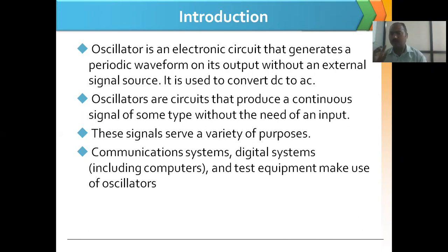Due to that positive feedback, whatever the random signal is, it is again and again applied from the output to the input. Due to that, after a very small time, in a microsecond, there will be a formation of the sine wave. This will happen in the case of your oscillator.